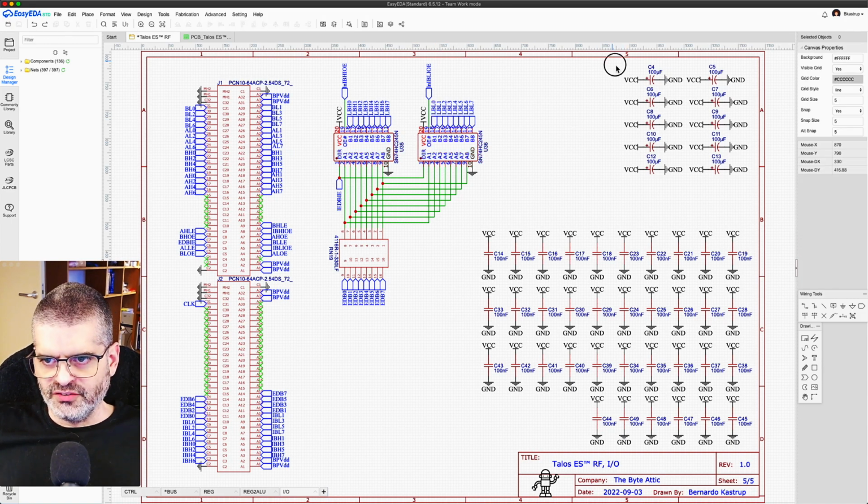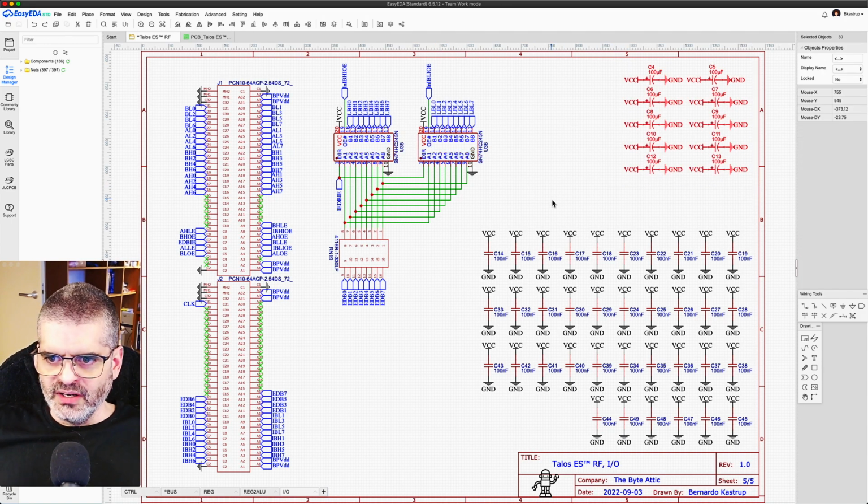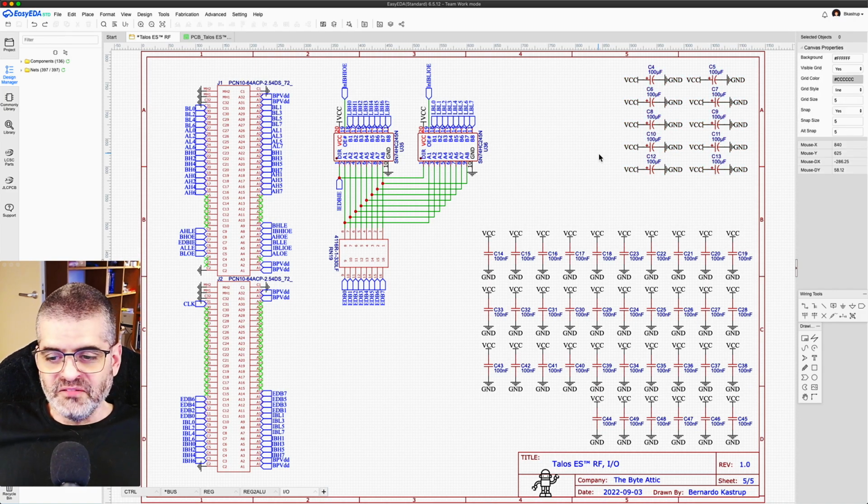And this is just 10 decoupling capacitors for a board that is 24.4 by 24.4 centimeters. About ten 100 microfarad decoupling capacitors should do. This is really a rule of thumb. To really know what you need, you have to follow the power distribution network and calculate the bottlenecks.